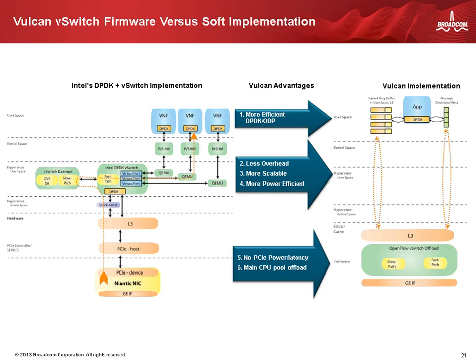And this consumes quite a lot of the CPU, and it involves quite a bit of latency, and this is one of the things that limits the throughput for particularly data plane applications. The ideal is to just have the packets go directly into the user memory space and have no real overhead for the packet. So the performance for virtualized functions is exactly the same as bare metal functions or applications that owned the physical interfaces. So that's what we've done with Vulcan. We've put in some coprocessors and acceleration, essentially in the SoC, that allows us to pre-classify and DMA the packets directly into L3 and into the memory space of the guest. And this eliminates all that overhead that exists today.